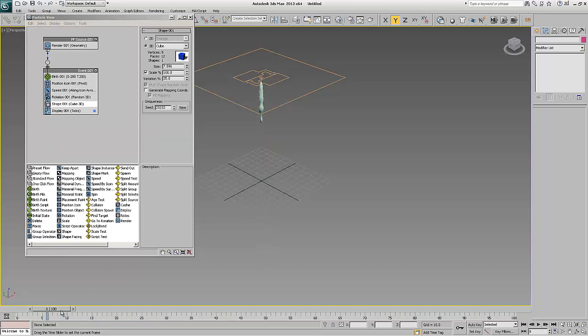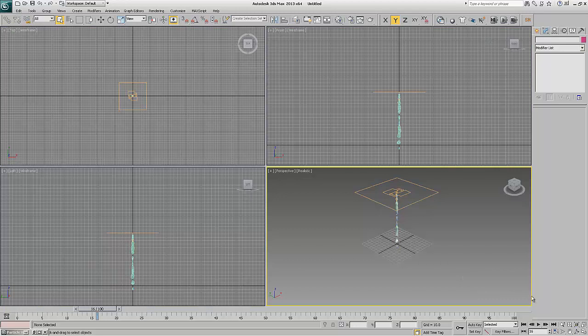Okay. Now, I've learned over the years that when it comes to particle flow and collision objects, it's always kind of an average. It's not ultra accurate. And so what I do is I've learned to set up my particle simulation, get that looking correct, and then I build my piece of geometry around that solution as opposed to the other way. So what we need to do first is build our little piece that's going to have a groove in it.